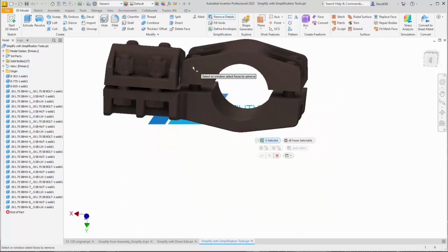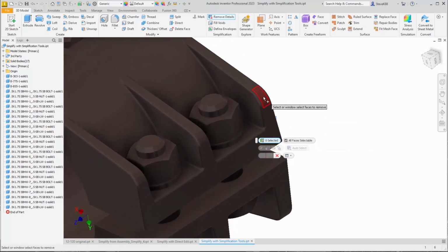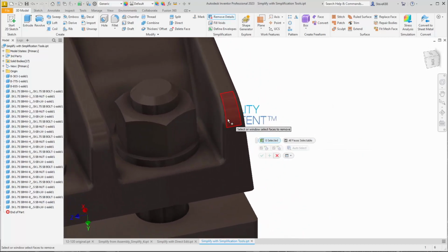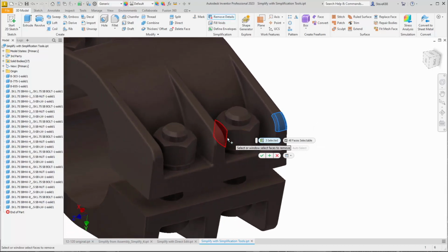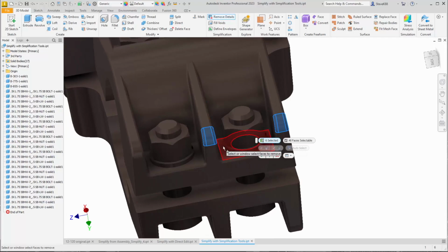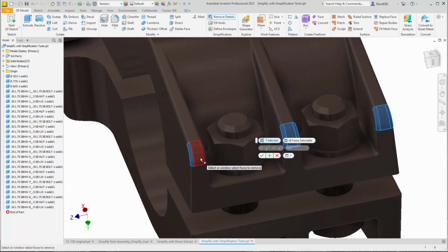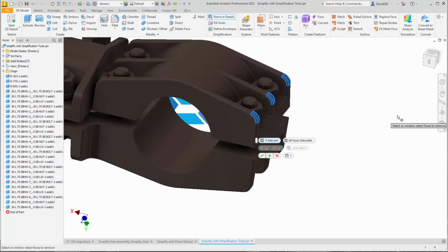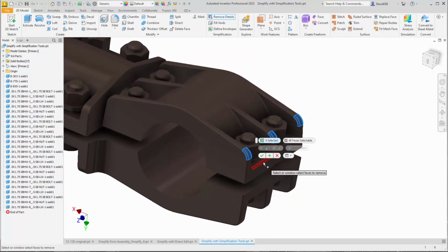I'm going to just go through, and I want to make sure all faces are selectable. And I'm going to start selecting a face. So if I come up here and select the face, I want to select the face up here. I'm going to move details here. Kind of like what we did on the other one, I'm having to pick the radius on the outside as well. Whoever made this originally, the database remembers how it was made, and I think the fillet was added after the fillets on the outside edges were done. So I'll say OK to that.